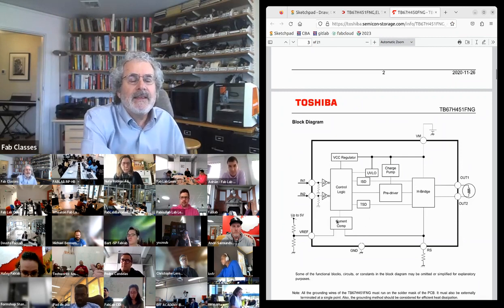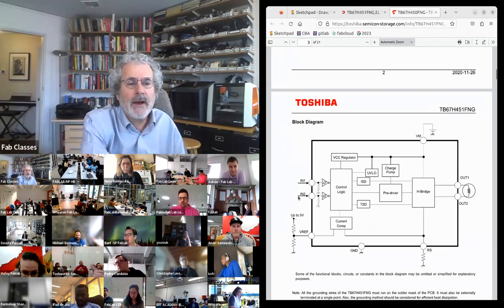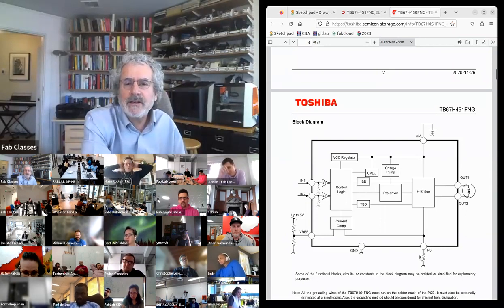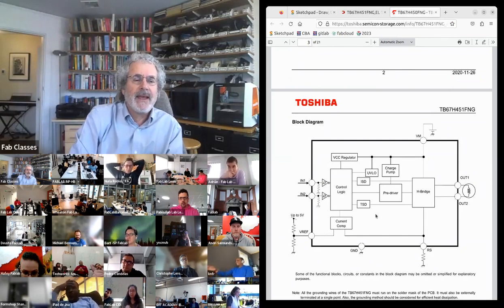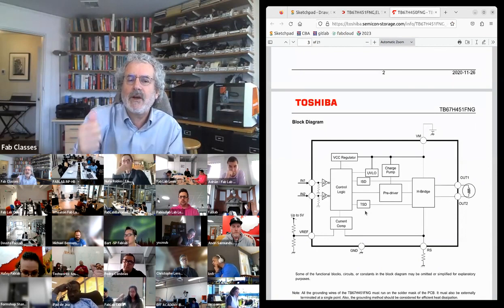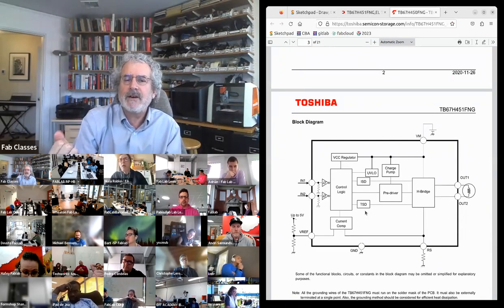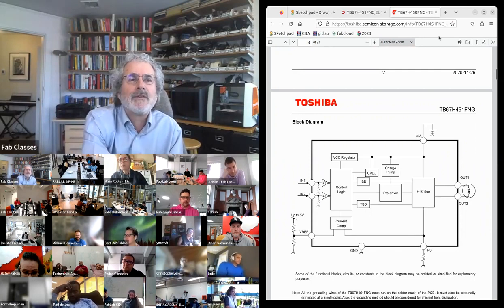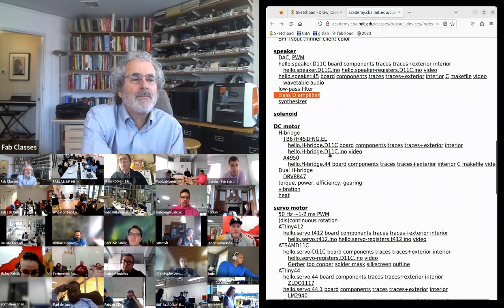Then this has a comparator. Because we want to pulse width modulate, you can pulse width modulate in software, or you can put a load resistor here and the chip itself knows how to pulse width modulate. And then finally, in addition, it knows how to detect overcurrent or over temperature. And rather than killing itself, it'll turn off if you overdrive it. And so with that wonderful part,